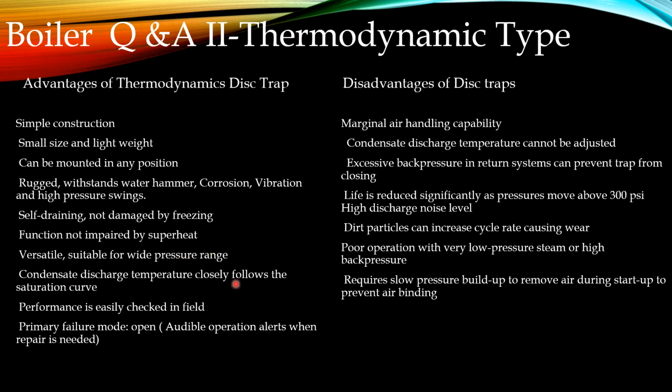Condensate discharge temperature closely follows the saturation curve. Performance is easily checked in the field. Primary failure mode open. Audible operation alerts that repair is needed. That is, when the trap is damaged, then you will get a continuous loud sound so that repair is needed. We can find it. So primary failure mode is open. It keeps the trap open.